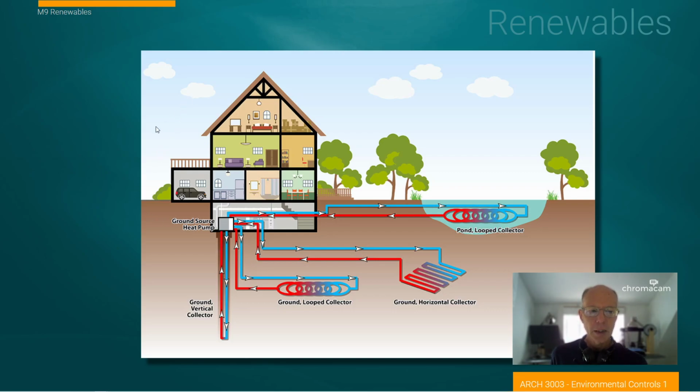So we need a source. We can heat a house from air temperatures, but the advantage of using geothermal heat is the heat that is already available in soil. And that's not insignificant. I don't know if I have the exact quote correct, but if you went down 9 or 10 feet below, the soil temperature stays at about 55 degrees year round. And that's a source of heat, and it's a place to disperse heat if we're talking about trying to cool something. So we have many ways to go about extracting that heat.